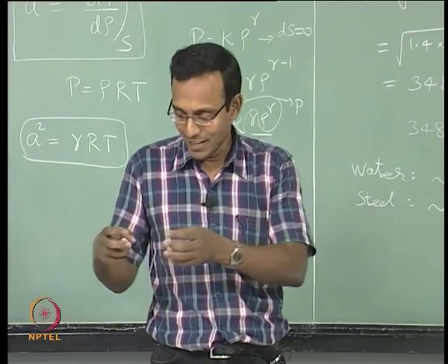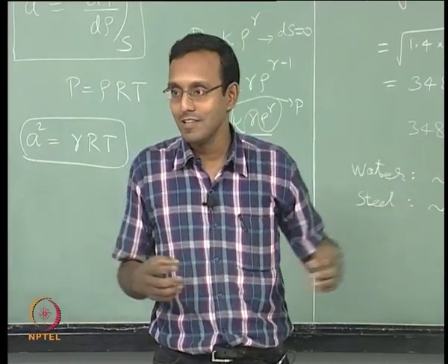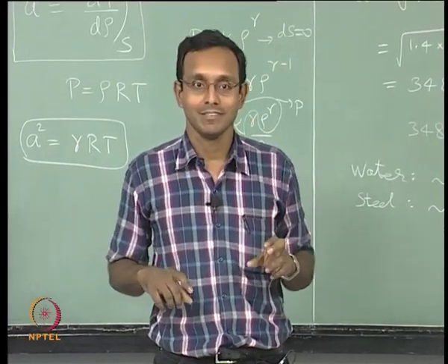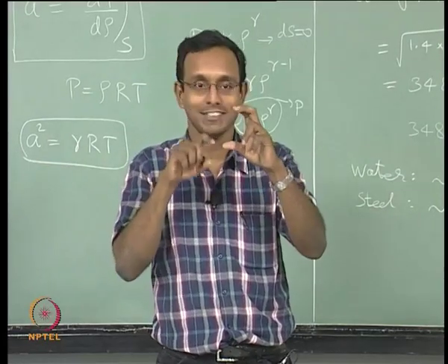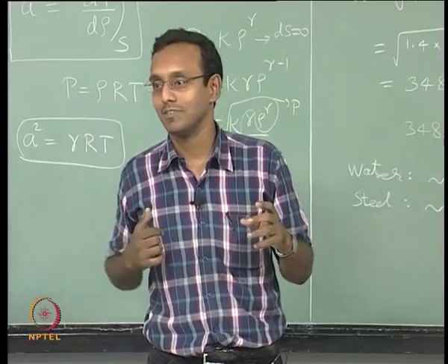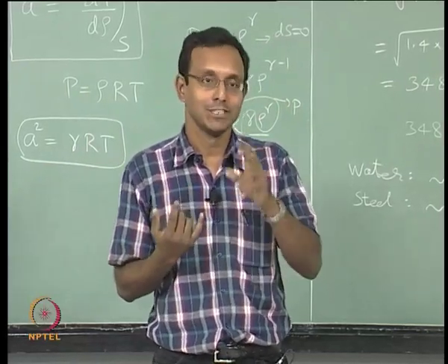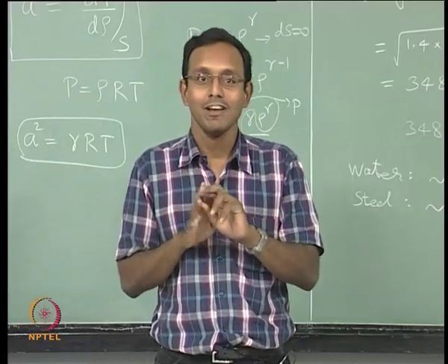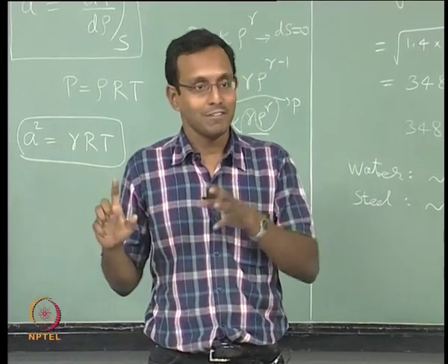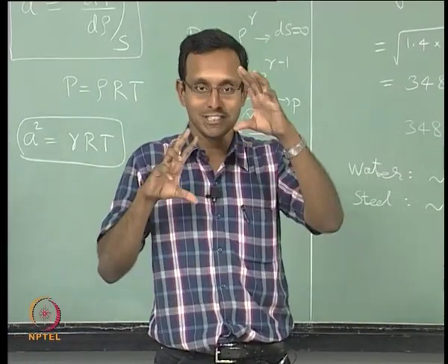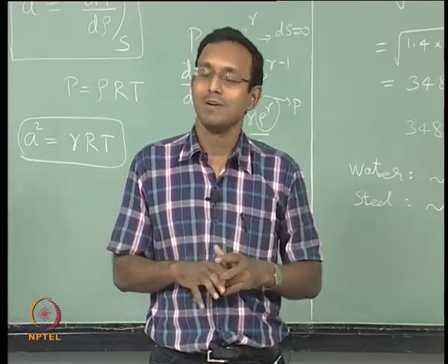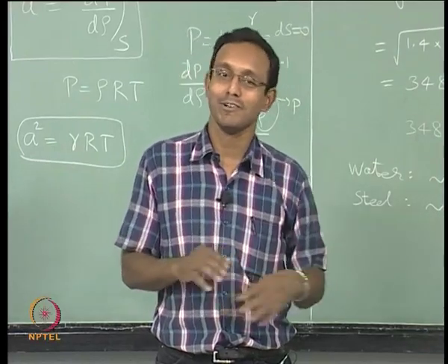But if I let these things go long enough, eventually these two waves will start talking with each other because of viscosity. There is a pressure difference here and these things will start happening the other way. There are a lot of other processes which we neglected in this problem. We said there is no shear effect, there are no other normal forces happening inside the wave, all kinds of assumptions are used in here. If we take into account other stuff, after some long distances this wave will just diminish in magnitude, that is what will really happen. But that is more of an acoustics perspective, we do not need to think about it.